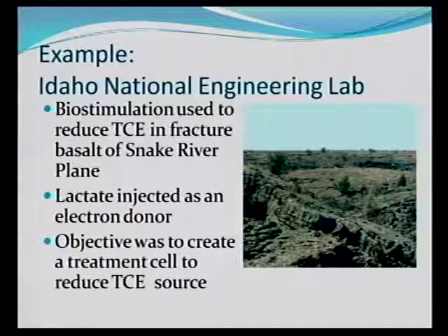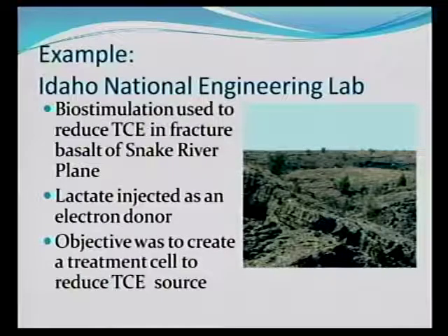They're either taking an electron off of, well, sometimes we talked about last time, you can get co-metabolism. So sometimes they're not even trying to eat the stuff that we want them to eat. So they're not trying to actually destroy the TCE, for example. But if they're in the process of degrading something else, they'll create enzymes that, in the process of destroying this, in this case lactate, they will create enzymes that destroy the TCE as well.